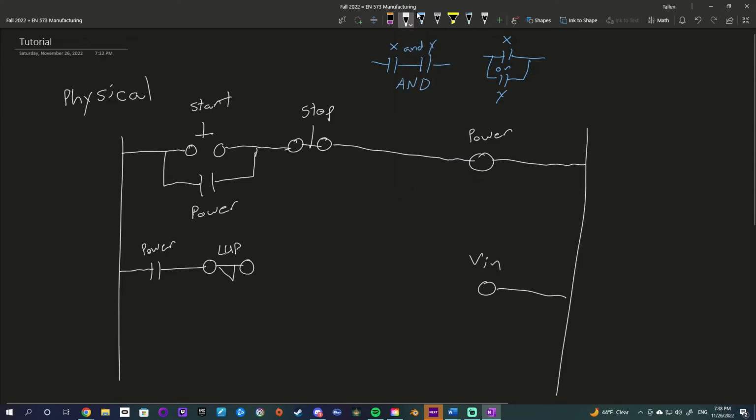So the last thing that we don't want our tank to fill during, and I'll explain why later, is if we are currently emptying our tank. So these are the three things that are going to keep our tank filling. We need power from this. We need to make sure that our tank is not already full, and we want to make sure we're not outputting anything. So as long as those three statements are true, it is going to start filling up our tank over here.